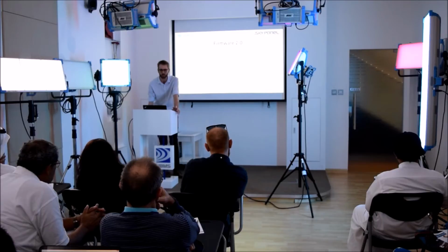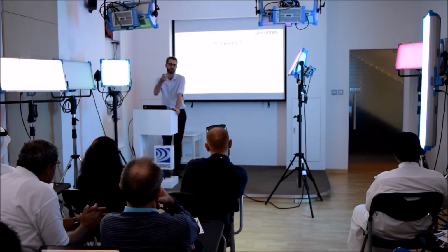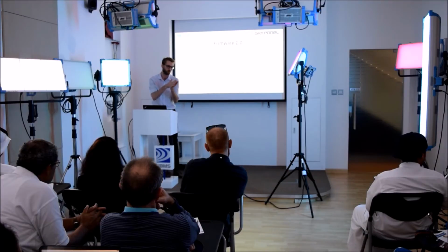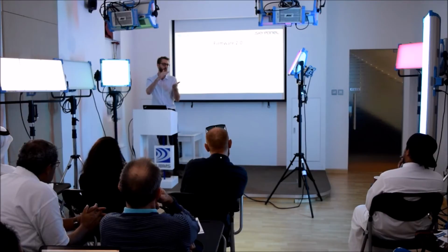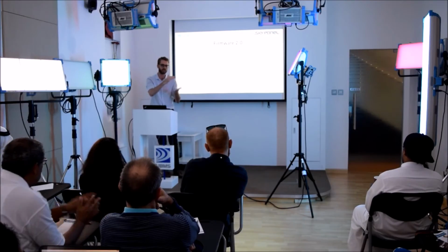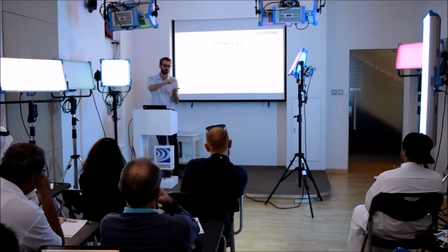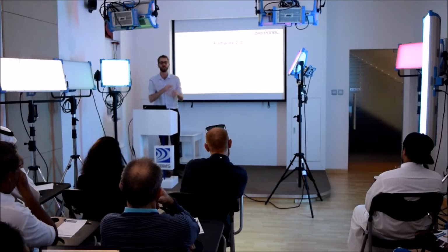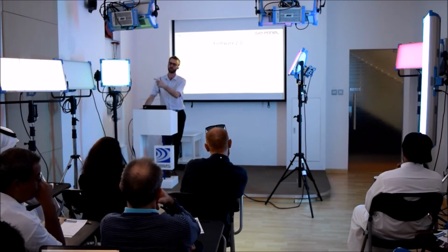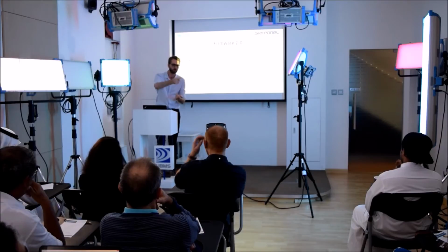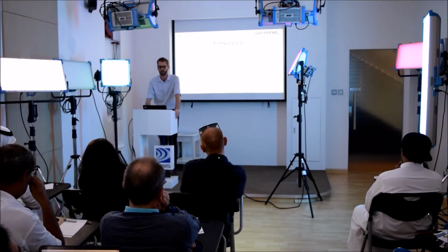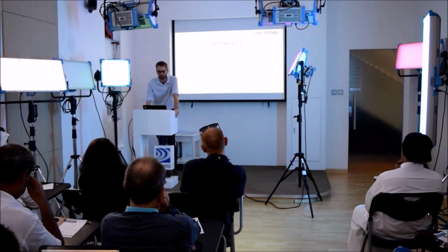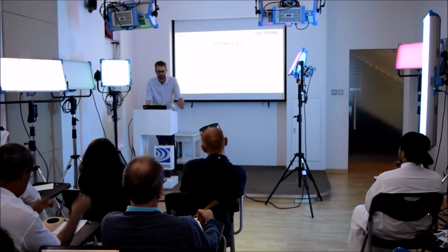And sometimes with LED panels, when you dim them down to that zone between 1% and maybe 15%, in some cases there's not so many steps at that low end. So it's a really small move of the knob to go from 1 to 15, but you want to be somewhere in there. Well, there's a low end mode, which gives you more control or more movement on the intensity knob in that low light zone. That's useful when you're dealing with low light situations where you need to keep everything dim.